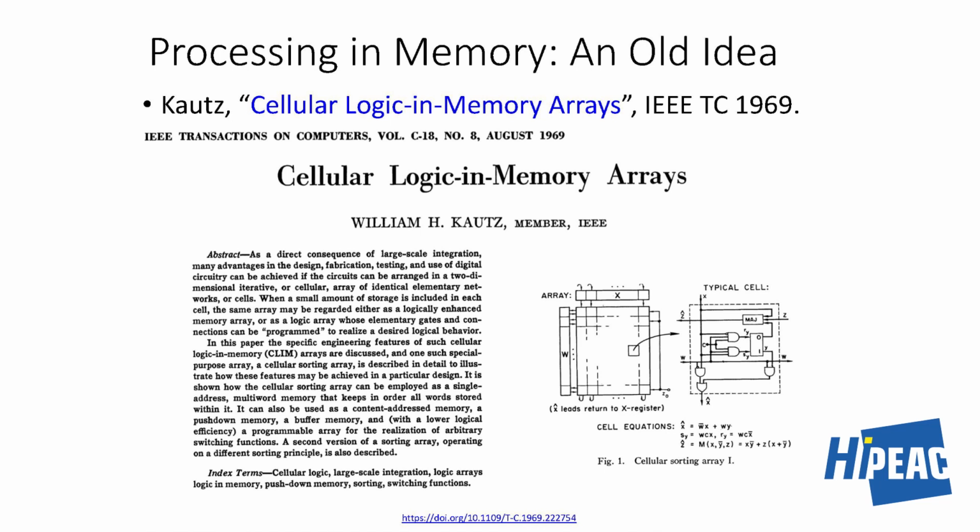But in 1969, they proposed, this is very interesting. They went very deep. With every memory cell, they integrated a majority gate. Majority gate is a universal gate. And once you have a majority gate, you can do pretty much everything, right? So that was the very first paper, if we date it back, which talked about in-memory computing. I call it in because you see this is an array of bit cells, right? So it's not the memory architectures we are used to today.